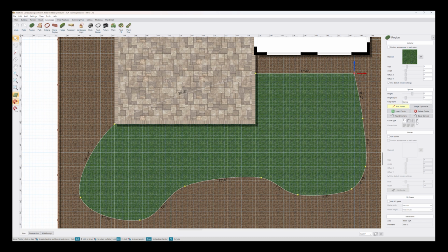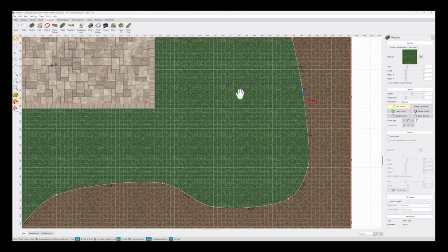There are two different options to the right, which allow you to use wings to finer tune. So if we go to this curved one, it comes up with these little handlebars or wings, so you can fine tune what that looks like on an angle, or this one to fine tune on a curve what that curve looks like. So it's a little bit finer point dexterity practice needed to be able to do this, but you can get pretty cool shapes as a result.